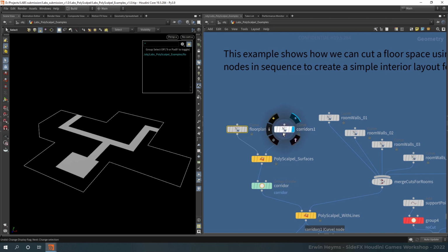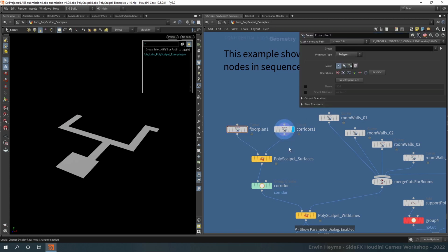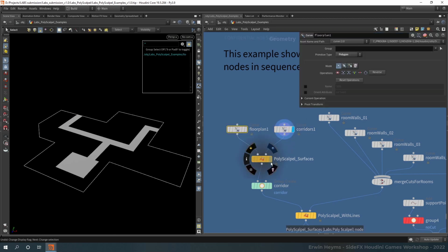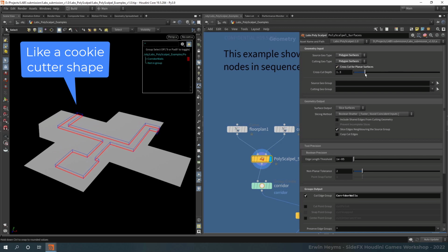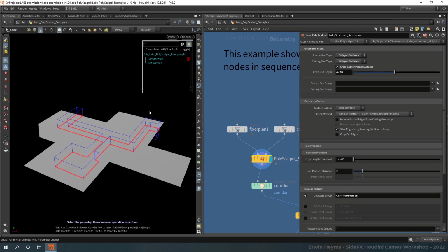These are two meshes, basically polycurves, right? I overlap them, and I set the tool into cross-cutting mode. Cross-cutting mode allows me to cut using a hull from the original geometry, basically in the cross direction of the geometry itself, and it will then cut the other geometry with that.